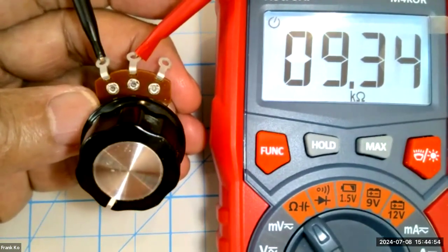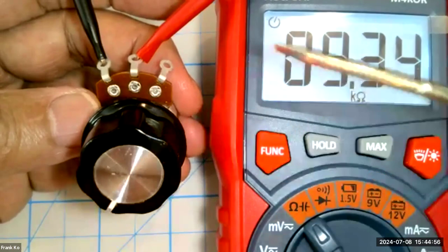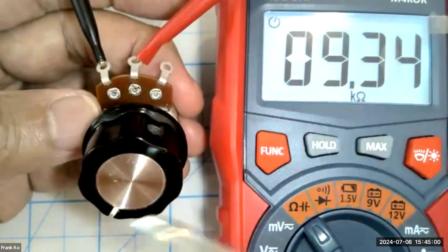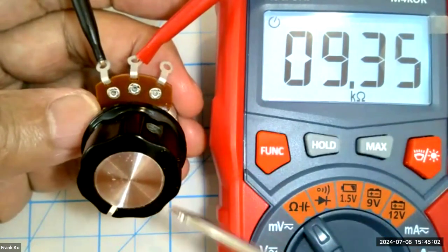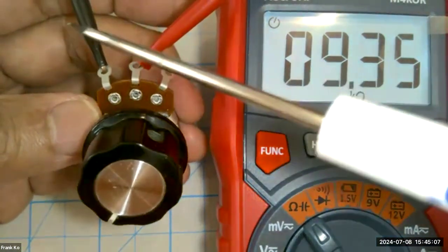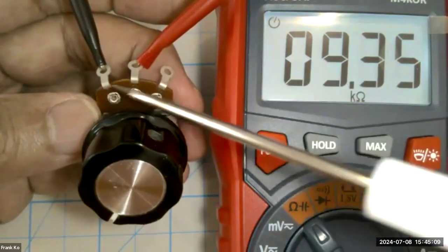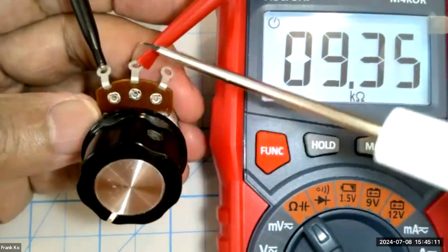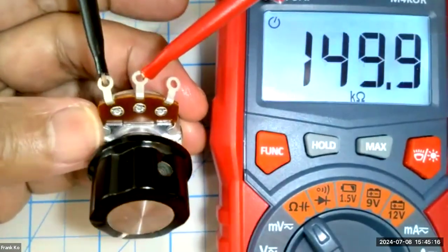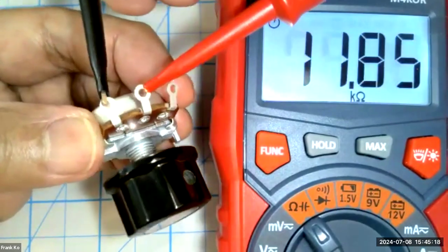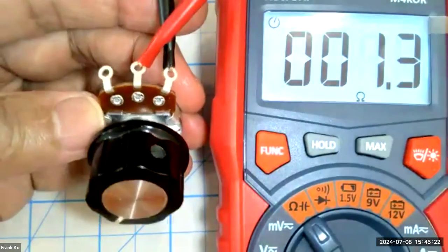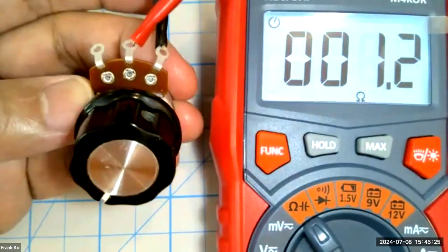It just means that this particular knob in its rotation happens to be measured between these two posts. If I want this to rotate clockwise in an increasing fashion, all I have to do is switch my mini hook from this outside post to this outside post. I'm going to keep the red where it is on the center post, but now I'm going to switch the outside post connection to go from here to here. Okay, so now I'm on the outside post, and voila, check this out.